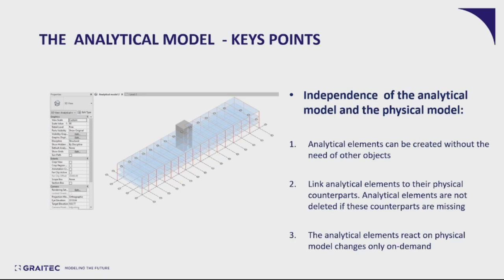The analytical model is independent of any physical model that exists in Revit. The analytical elements can be created without the need of other objects. You can link the analytical elements to their physical counterparts. Analytical elements are not deleted if these counterparts are missing. And the analytical elements react to physical model changes only on demand.